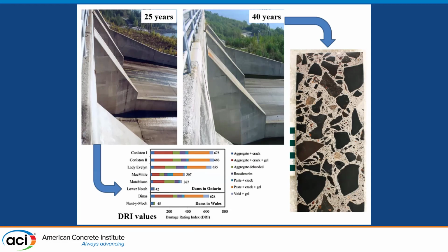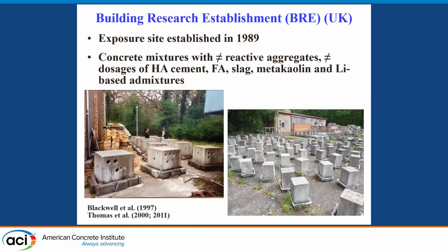But in most cases, in recent years and for the past 2 or 3 decades, researchers have been using outdoor exposure sites for evaluating the effectiveness of preventive measures against ASR. And the work of the Building Research Establishment, BRE in the UK, by Mike and the team there was very, very important. They established a number of exposure sites back in the late 1980s, where they evaluated concrete mixtures with different reactive aggregates, dosages of high alkali cement, fly ash, slag, metakaolin, lithium-based admixtures.